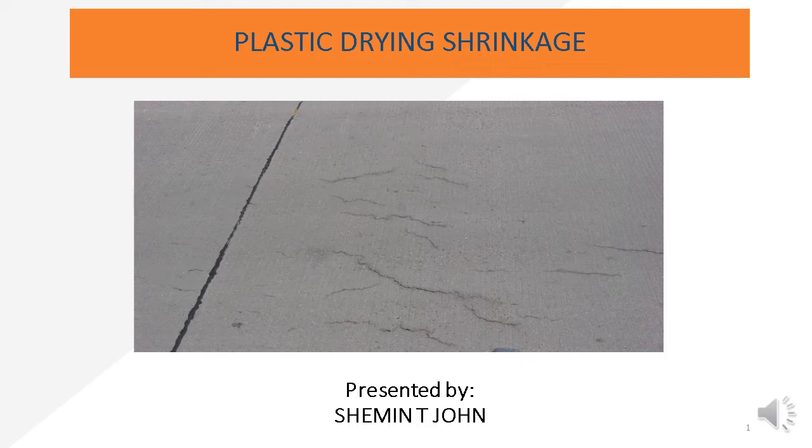Due to this loss in moisture, tensile stresses are developed in the structure, and it can form cracking on the surfaces. This is a durability issue, and it can affect the long-term strength of concrete.